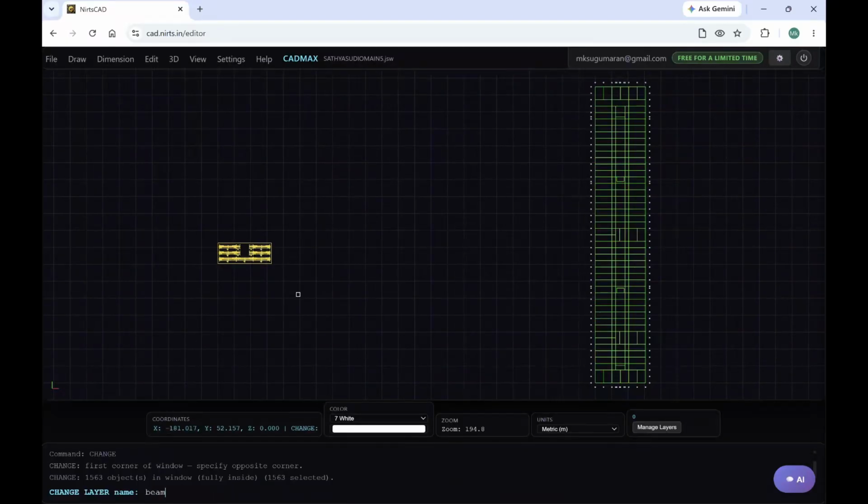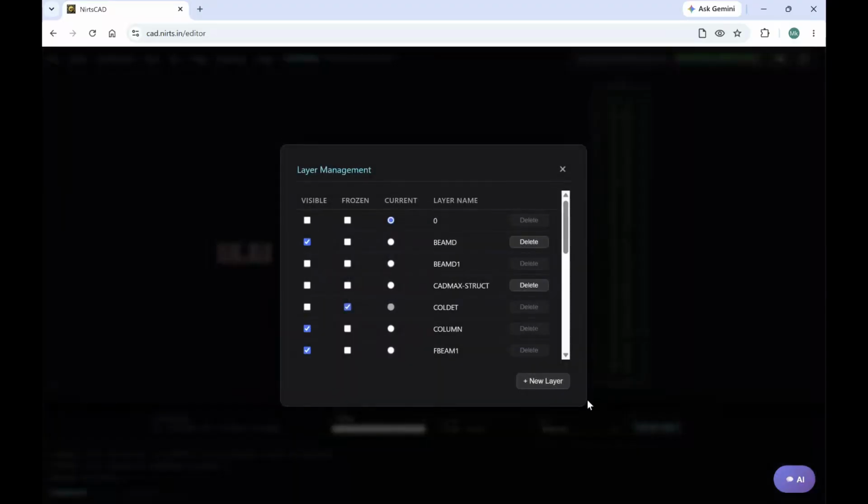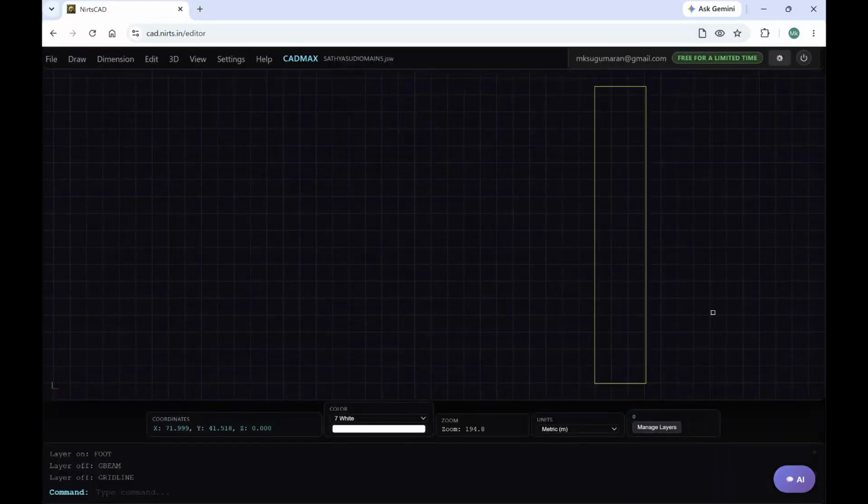Using XData command, see the size of footing and soil pressure. The size is almost touching outer columns and soil pressure is 59.64. We can adopt it as 60 kN per square meter.